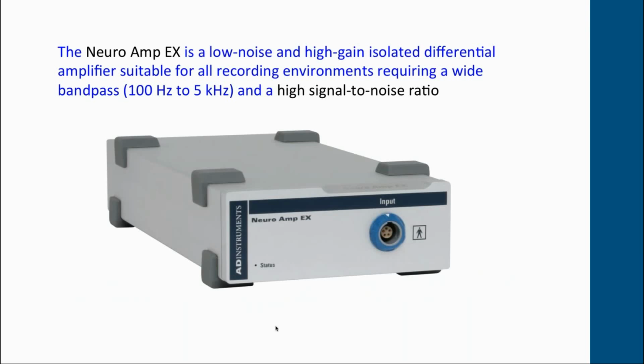The Neuro X is a new type of amplifier, and I was involved as a consultant providing the system specs and testing all the prototypes, and it is a very good low noise amplifier. As you can see here, it's got a wide bandpass, 100 Hz to 5 kHz, and importantly a high signal to noise ratio.